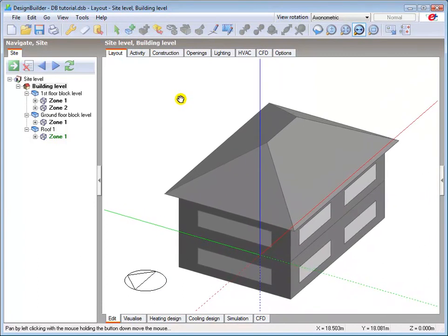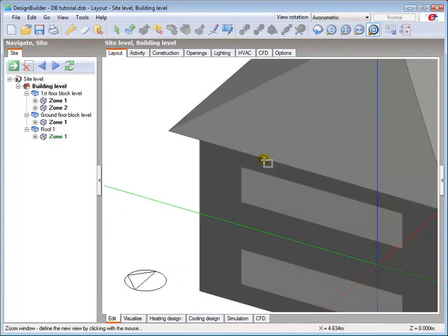You can select an area of the screen using Zoom Window. Left click on the first corner, hold down the left button and choose the area to zoom into using the standard Windows click, hold and drag technique. Cancel the Zoom Window command using Escape.